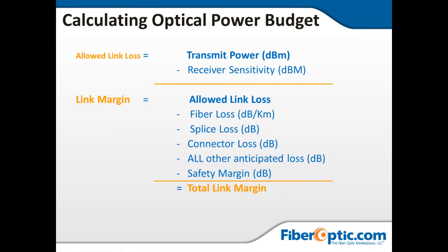Like I said, we can give you a much more detailed form. Just give us a call or send us an email, and we'll be glad to provide it for you. And that is the total link margin. So you see, although this can get very technical and complicated, it's based on a very, very simple formula: power. As power goes out over distance and hits connectors and runs through the glass over time, it loses power.